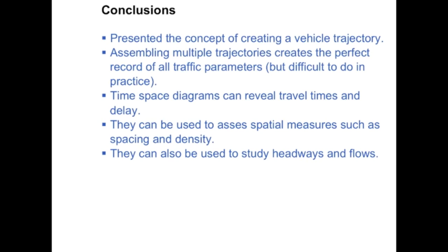So in summary, I presented the concept of creating a vehicle trajectory. Assembling multiple trajectories creates a perfect record of all traffic parameters, and time-space diagrams can reveal travel times and delays. We can also use them to assess spatial measures such as spacing and density, as well as point-based measures such as headways and flows.